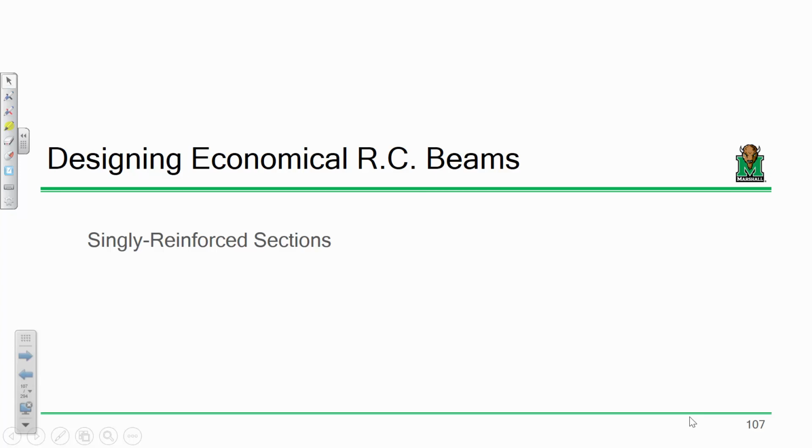Because we're getting to a point where really what we care about when we're talking about design is the width of the beam, and not the height, but that effective depth, the distance from the top of the beam to where the steel lies. So As over bd is sort of a percentage of how much steel. So if you have a rho value of, let's say, 0.02, you can sort of think that 2% of that section is reinforced.